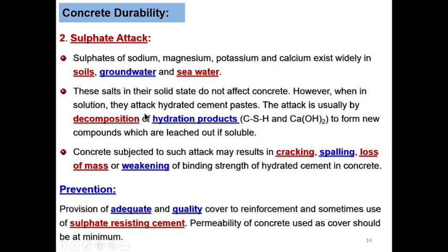This one is unlike chloride. Chloride attacks the reinforcement, it does not attack concrete itself. But this one attacks concrete itself because it attacks the products of hydration, usually the calcium silicate hydrate and calcium hydroxide. So when it dissolves the products of hydration, it forms new compounds, and mostly those new compounds are soluble. So because they are soluble, they will be leached out.